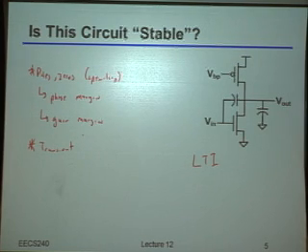Okay, you could certainly test the step response. That's actually a reasonable thing to do. There's maybe not necessarily simpler, but a more common type of solution that people come up with as well, which is very much related to the step response. Yeah, there we go. Basically, you just put a pulse of current or voltage or whatever it is into the thing, right? And then if the thing is going to oscillate, well, you'll see that that small pulse caused it to actually start going bonkers, right? And if not, you should see that within a reasonable amount of time, whatever the pulse was went away. Basically, you went back to whatever that nominal operating condition actually was, okay?